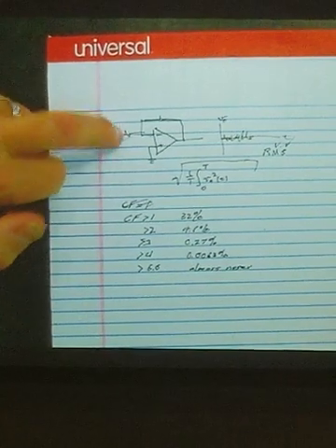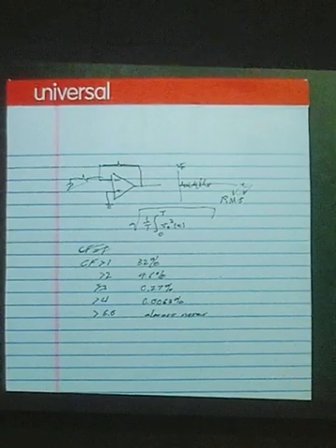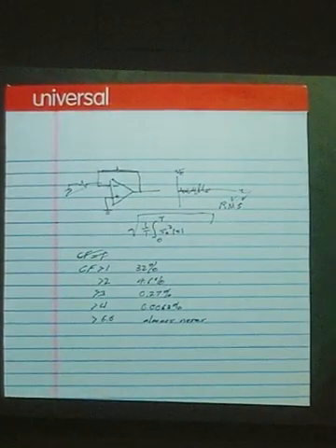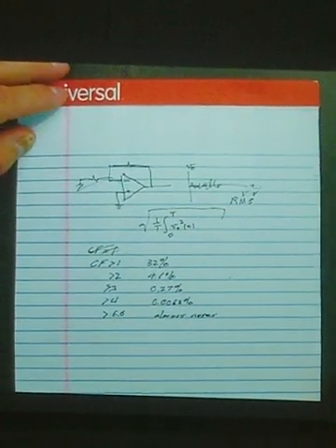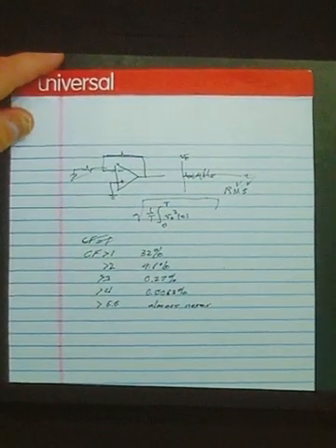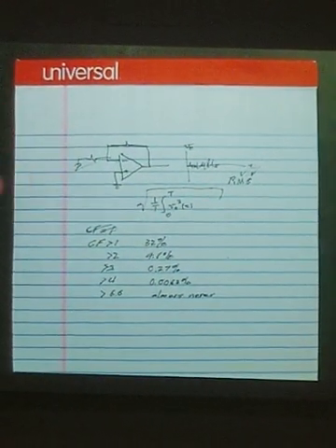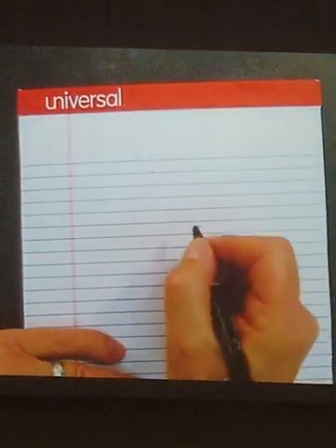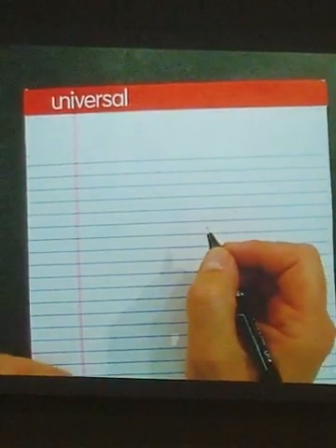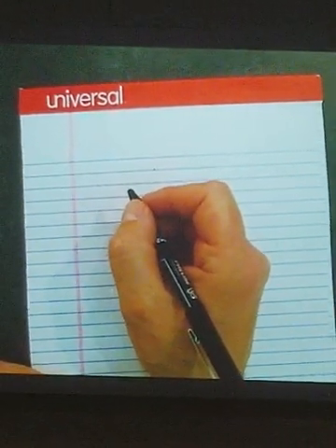So this is all, again, just the device under test. And we can swap that out for some other op-amp that's lower noise, or we can pull some tricks to get higher noise circuits, etc. Okay? But that's how we think of the noise in there. Now, how do we calculate it? Well, that's where we come up with power spectral density. And that was what those graphs that I showed you on the data sheet were earlier.